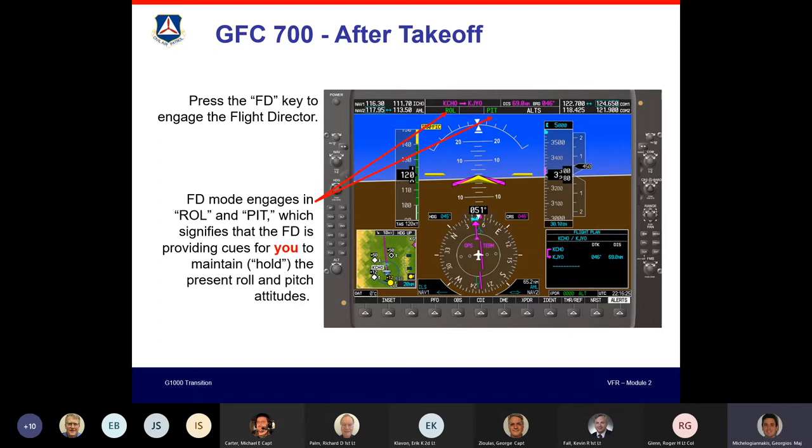And also, the autopilot also controls the trim. If you try to use the electrical trim, it will disengage. But also, that breaker is important because if you have a runaway trim situation, the checklist calls out to pull that breaker. Not as the first step, but as you go down the checklist. And that's actually a new item in the new Form 5 is to demonstrate that.